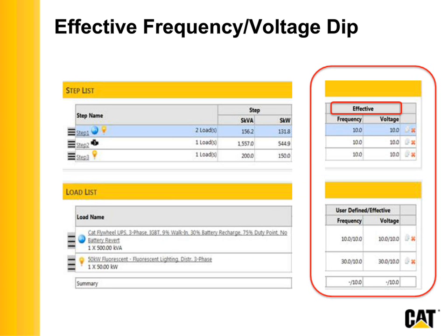If you need to do that to align with your spec, okay, but if you don't have to, multi-sequence your load steps. Have more than one. In addition to that, make sure that you sequence your loads that have the tight or the restrictive frequency dip or voltage dip later. And here all we're doing is showing you that again.